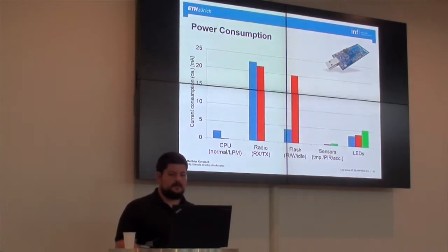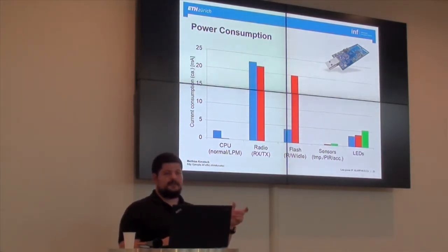Interesting what you see here, for instance, is that receiving is even more expensive than sending. In this case, for this radio chip, it's because of the low noise amplifiers that need more energy than sending the symbols, where you only have to have short pulses to generate the symbol. And I think in newer generations they could change this again, but this is more that they send with more power to have fewer losses actually. So what do you do?